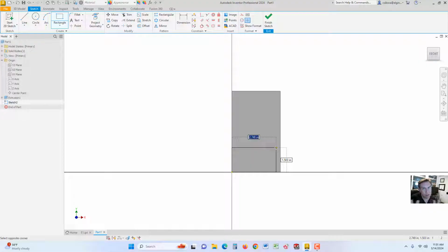Now, I tell my students who are new at this, don't think too deeply about it. It wastes too much time when you're first learning. It's something that you pick up over time generally. But in this case, we wanted to follow that 3-inch width. So what you could do here is hover over the right edge, and you see a little symbol to the right of your pointer near the dimension, and it automatically goes to 3. You don't have to type in a value. Actually click on that edge, and it will assume now it's locked in coincident to that edge. So if we ever widen this, this block that we're creating now will widen with it.